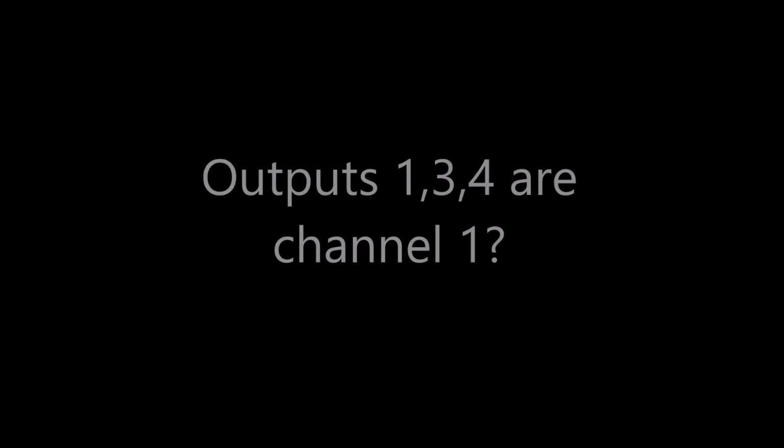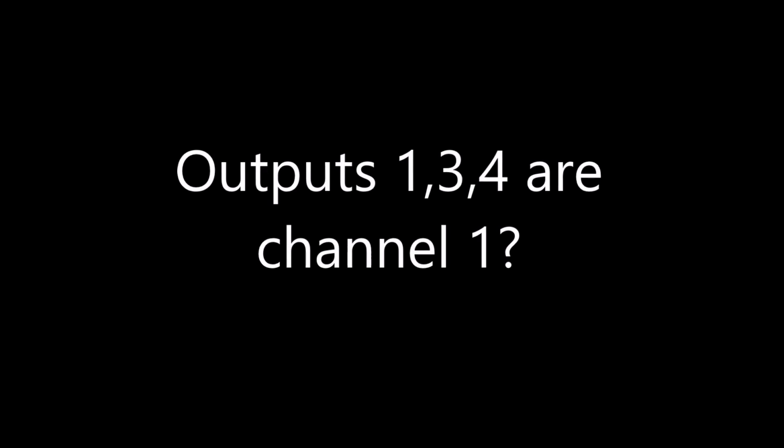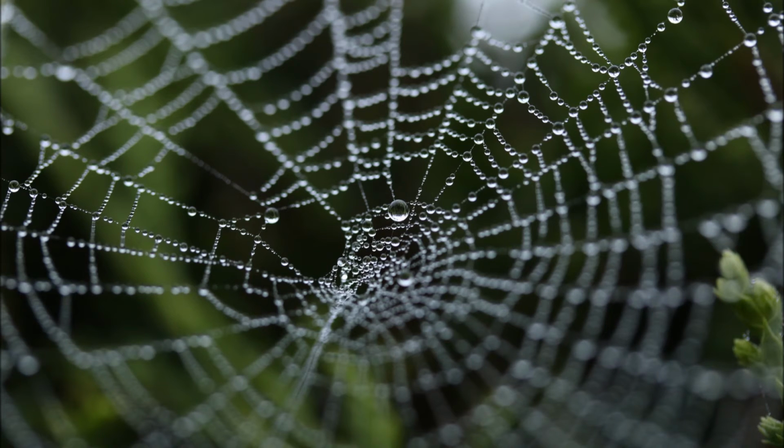This might be specific to our unit, but outputs 1 and 3 and 4 are all channel 1, and output 2 looks like it's channel 2. So hopefully that helps you avoid a common trap that we've all fallen into with signal generators and logic.